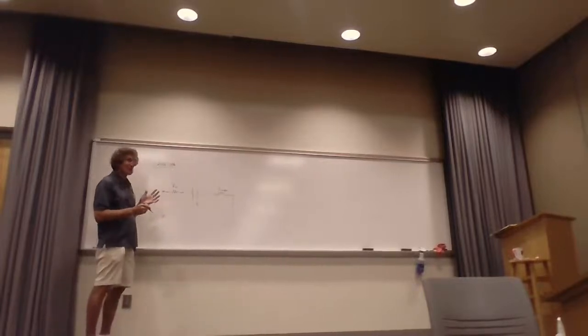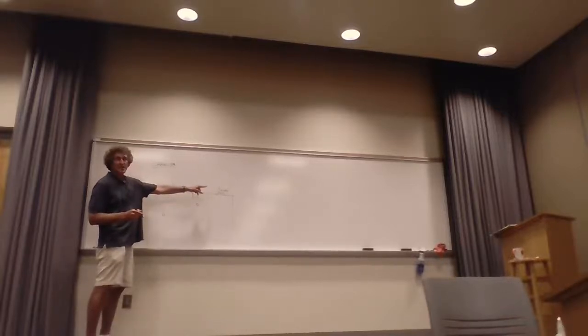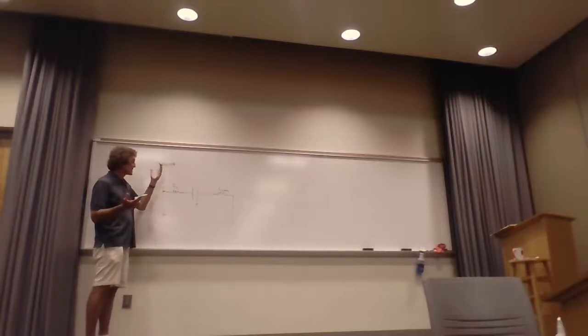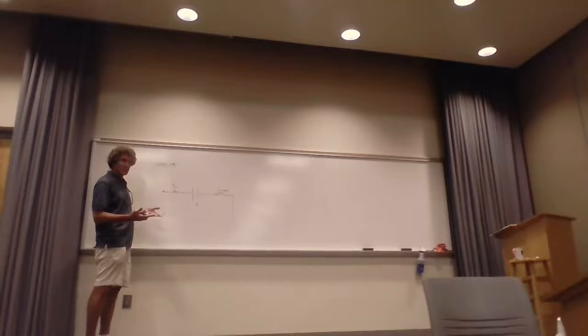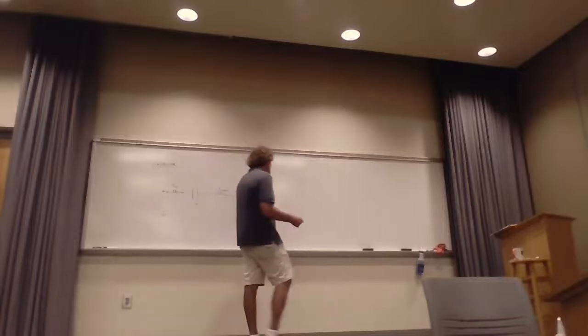At low frequencies, the impedance of this, as you're going to 0, is going to infinity, isn't it? Because you have a capacitor in series. At high frequencies, it's going to infinity too because of that inductance. Somewhere in the middle, when you get resonance, you have a minimum, and that would be caused by that resistance because the capacitive reactance and the inductive reactance will cancel.